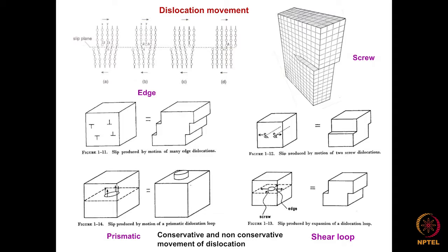In this sample there is one dislocation present here. Okay. If you look here, 1, 2, 3, 4, 5 layers are here, correct? Top also 5 layers are there. What is essentially being done is that with respect to the bottom, the top layer has been applied some stress so that it is pushed, so that the layer at the back maintains a continuity. So, this layer has been pushed by one lattice translation vector. Then it has introduced some defect within the material. This is what an edge dislocation is.